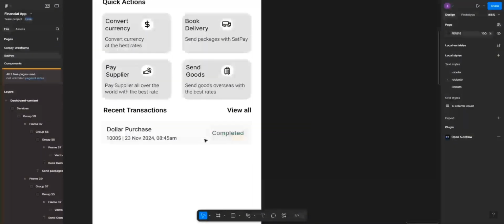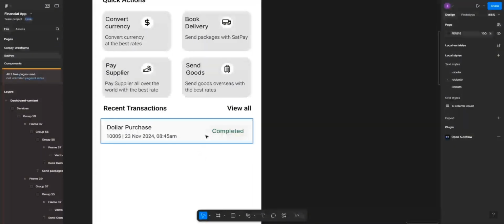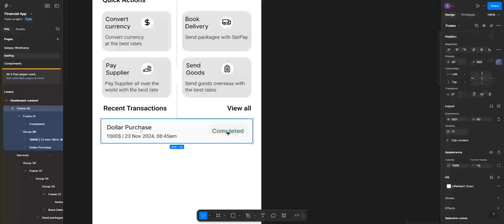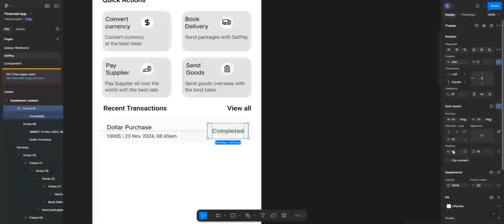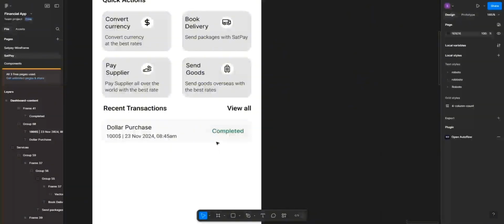Okay, so let's zoom out. Now to move faster, let's select this frame again. There's one or two things to modify there. The height of it is 10. Let's change it to 8, and also here 8. So I think that is fine. Don't tamper with this size, should remain 10. Just the height that we're going to change, which is 8, is fine.